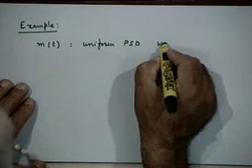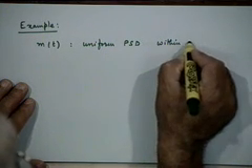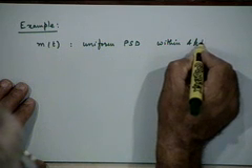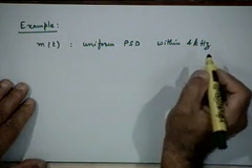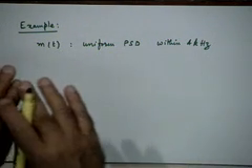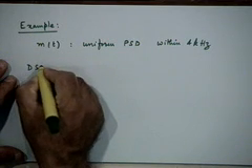So it is defined in terms of its power spectral density function in the frequency domain, right? And let's say it has a uniform power spectral density function over its bandwidth, which is assumed to be 4 kilohertz, right? That means the power spectral density function is flat, extending from minus 4 kilohertz to plus 4 kilohertz. That's what it means. Let's say we are working with a DSBSC system.